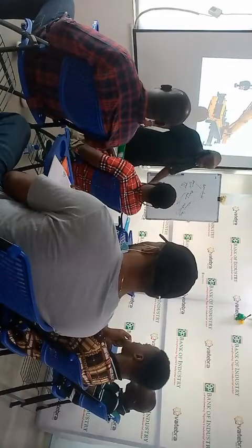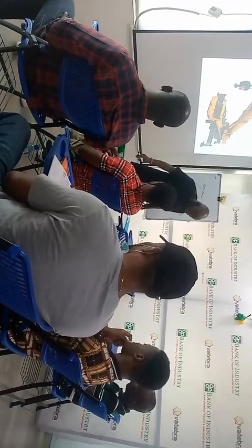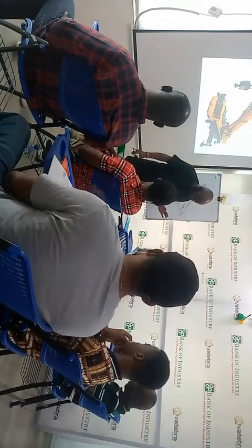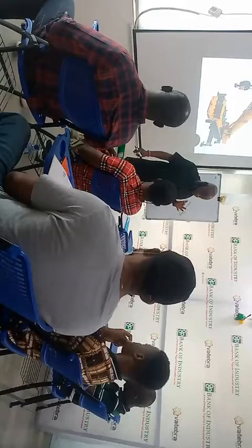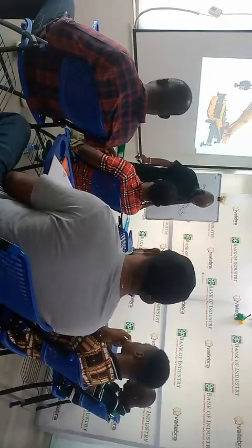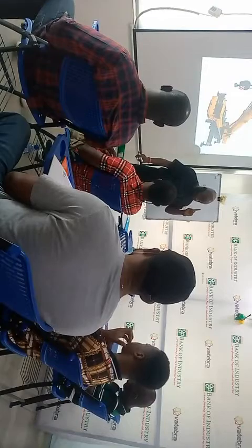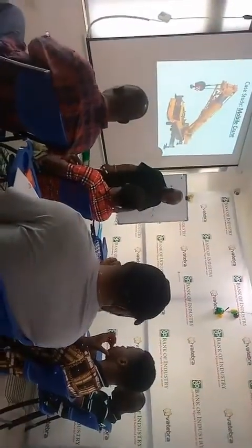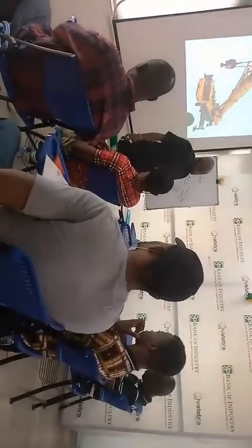Boilers, but that one is for another day. Then these questions I said is: has the lifting operation been performed using the lifting machinery? That is the first question you ask yourself. Then if no, that machine must be tested in accordance with the maker's documented procedure.